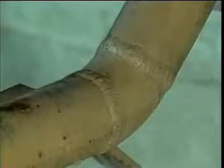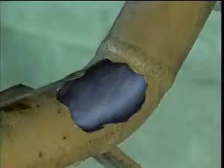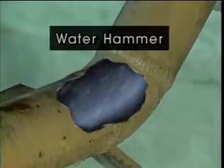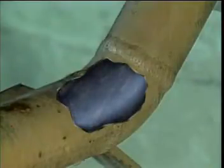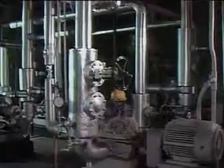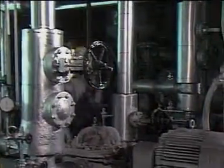When the pulse encounters bends or restrictions in the piping, it slams into them, causing a shock to the system known as water hammer. In severe cases, water hammer can cause piping to rupture, or it can damage other system components. By following operating procedures, you'll stand a better chance of avoiding these types of problems.